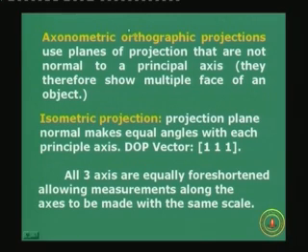That means you use planes of projection that are not normal to your principal axis, so you can place it anywhere in axonometric, but in the special case of isometric, it must make equal angles. What must make? The projection plane normal must make equal angles with the 3 principal axes x, y, z, and a typical example is the directional projection vector, which you can say is also the projection plane normal, given as 1 1 1, and the dimensions of the object along all the 3 axes appear to be equal and the same for the isometric projection.